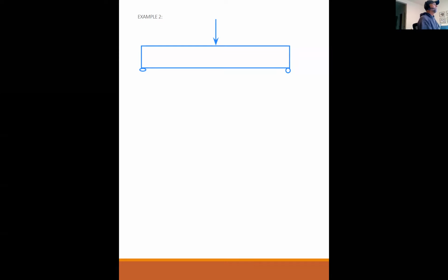Now, is it clear that if this is my situation and this is my load, that if this beam is going to crack, it's going to crack right there first? The technical term, why did it crack here at the bottom first, is because when you have a simply supported beam, and you apply a load that's coming down on it, like I show here, that produces a positive moment.